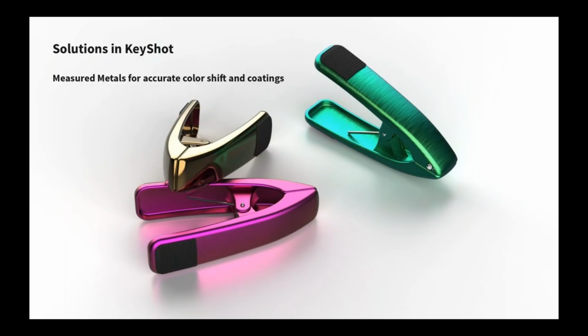Like a real anodized coating will always have some kind of a color shift depending on the viewing angle, and it's subtle, but I hope you can see that in the front facing surfaces like this blend, the color is more green, and as the surface rolls to 90 degrees basically, you get more of a bluish tint. You can see the same here. This highlight, which is facing straight to the camera, is kind of purple pinkish, and as the surface rolls upwards, you get more of an orange or red kind of hue. It's very subtle, but it definitely adds to the realism of the rendering.